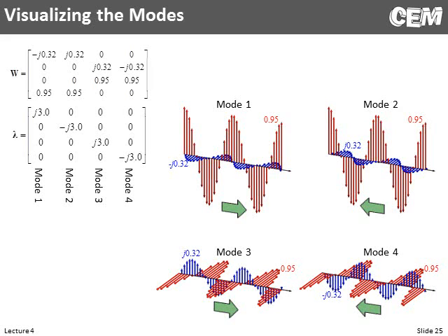And so if we were trying to draw these, take this first mode, we have 0.95 amplitude on the HY component. So here I'm drawing the HY component oscillating as it travels in Z, and its amplitude is 0.95. The EX component has a minus J 0.32, so it's a smaller wave, only amplitude of 0.32, and that minus J dictates phase. It's minus 90 degrees out of phase with the H. So that's a traditional picture of a plane wave, and there's a balance between E and H, which is clearly coming from the impedance.